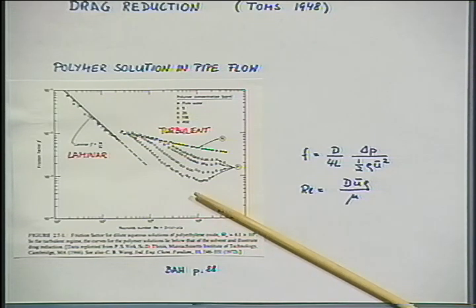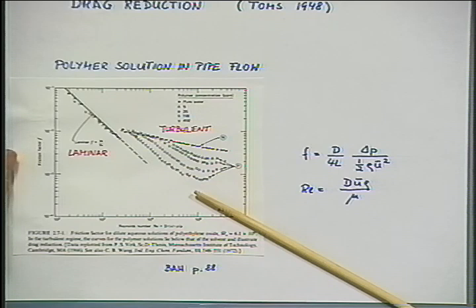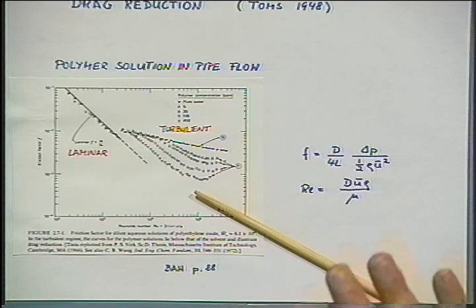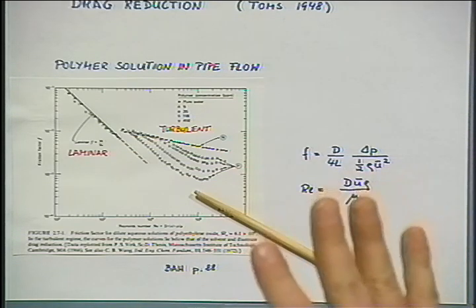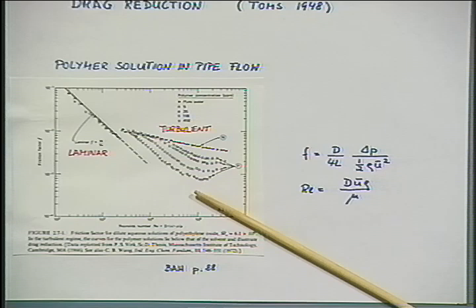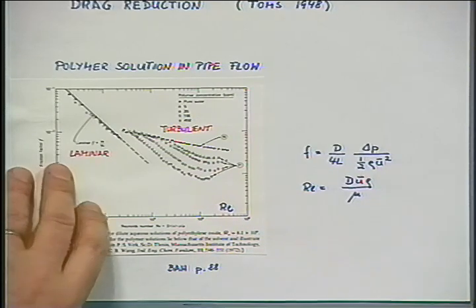Also, it's used in some cities with sewer problems. If you take a very flat city like San Jose or so, if there's lots of rainfall, there's not enough tilt to discharge all the rainfall. In this case, polymer can be added in small amounts to the sewer, and with the given small inclination in the city, you have sufficient discharge and you avoid flooding. So there are interesting applications.